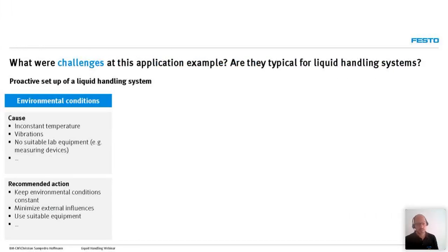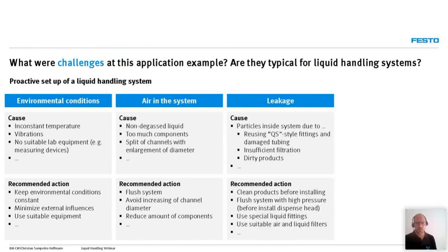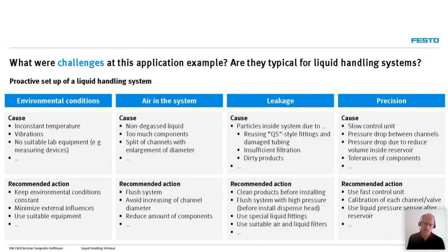So before I come to the end, I want to give you some notes about some challenges and how we can solve them. When we are talking about this pressure-driven dispensing approach, and probably also other approaches, there are circumstances where we do not get the right results. And more or less, we are talking about the same things every time. We have some particles in the system. We have some leakage because there are particles in the system. We do not take a closer look at the environmental conditions.